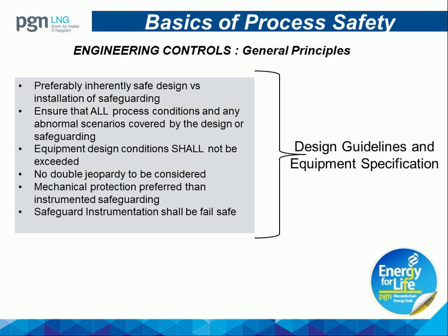So a bit more details on the engineering controls. It's a general principle that we need to have an inherently safe design instead of installation of safeguarding. So sometimes it's better to increase the design pressure to the maximum design achievable instead of having a pressure relief valve. That's one of the examples. There are a lot of things that you can find on this inherently safe design, but sometimes it's too costly to do that, or it is technically impossible to do that as well.